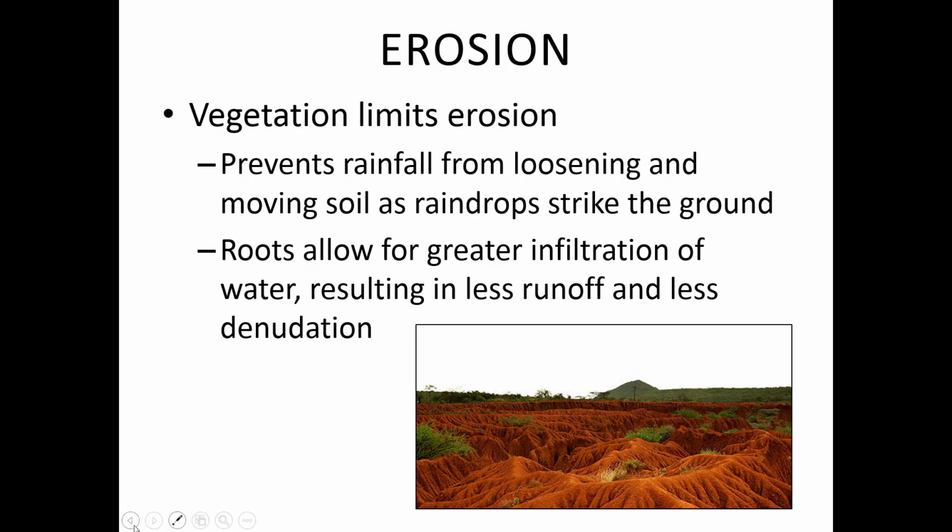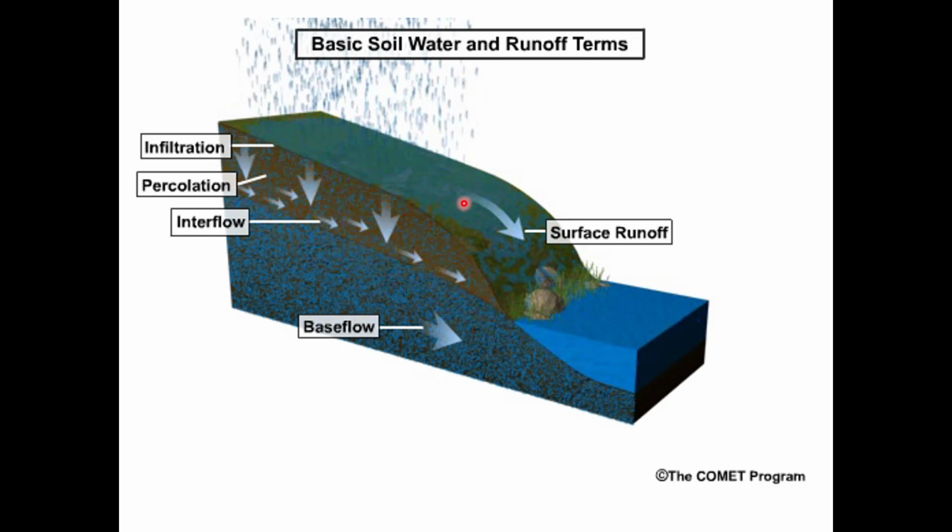What drives erosion is surface runoff. The energy of the water coming and falling on the land surface, if it doesn't infiltrate, then it does surface runoff. And when water is running across the surface, it can have a lot of energy. And just like with the stream dynamics, when water has energy, it will pick up earth material. That's what it does with its energy. And so you can imagine that this water running over the surface will have a great potential to erode the surface.